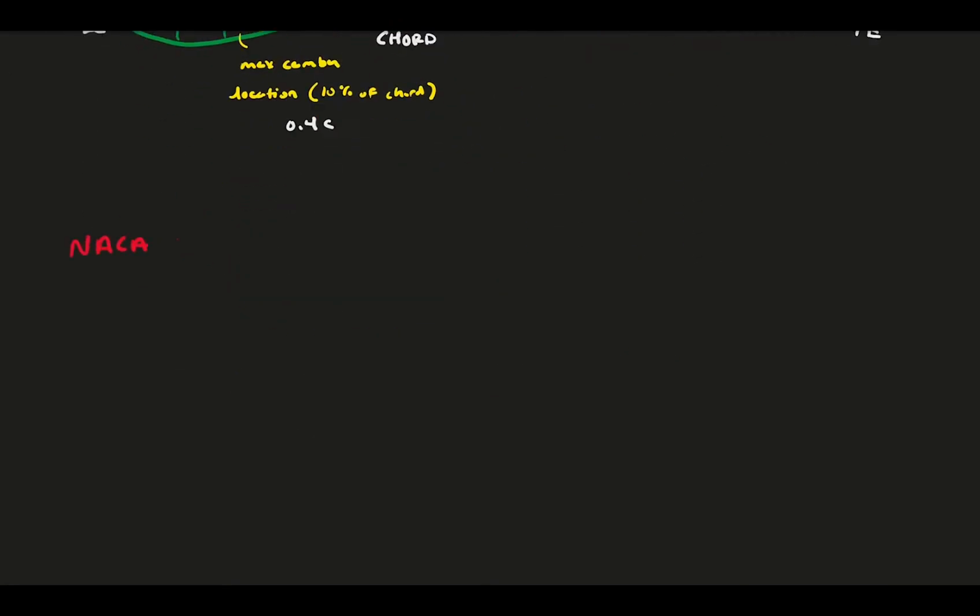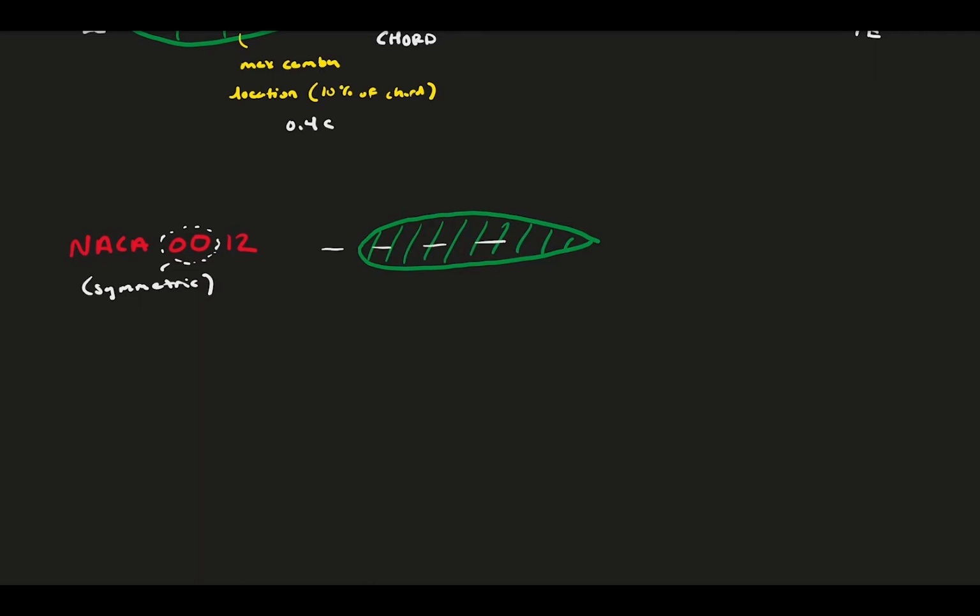There is a special subset of NACA 4-digit foils, where the first two digits of the 4 are 0. This means the foil has no camber and is in line with the chord. These are called symmetric foils because they are symmetric across the chord. Generally, symmetric foils are not as good for steady aerodynamics at fixed angles of attack. However, they are great for surfaces that are moving up and down, like an unsteady foil, or need to be neutral, meaning no lift at 0 angle of attack, like control surfaces.